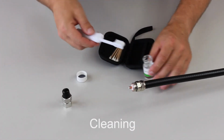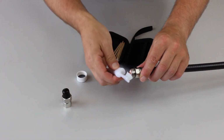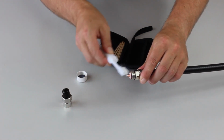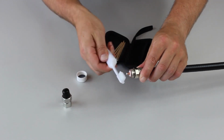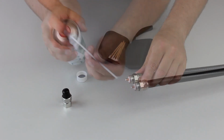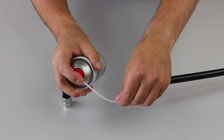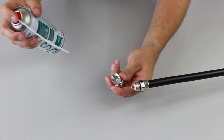Thorough cleaning is essential to enable PIM-free contact. Clean the contact surface and the inner conductor with a brush dipped in alcohol. Then use compressed air to clean small dirt particles from both the contact surface and the connector, and then dry them.